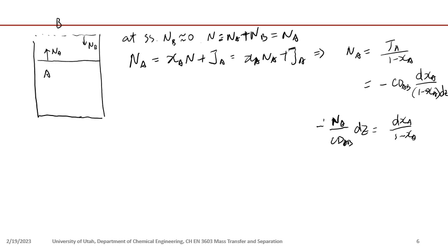But let's say we are talking about ground contamination, not in open soil. Let's say, if you like gardening, you like to grow strawberries in your backyard in a pot, and now you are applying some fertilizer. Similar problem, but now the boundary condition will be different, because in a pot, in the Z direction, you don't have infinite space. So the fertilizer will hit the bottom of the pot at some point. At the bottom of the pot, it's a no flux boundary condition. At the surface, you have constant concentration. So this is what I mean.